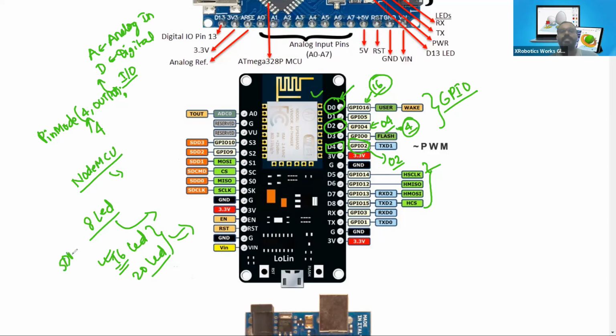So what we have to do in that case, we do have different SDA pins and SCL pins. SCL is the clock and SDA is the data pin. So we are going to address those 16 LEDs or 64 LEDs using the method known as I2C, IIC or I2C protocol. We are going to utilize it in future projects so that we can address 100 hardware devices connected to a single microcontroller. You don't have to buy a new microcontroller to accommodate other hardware devices or the input or output devices. We can do it in a single microcontroller. We just have to give them a physical address.